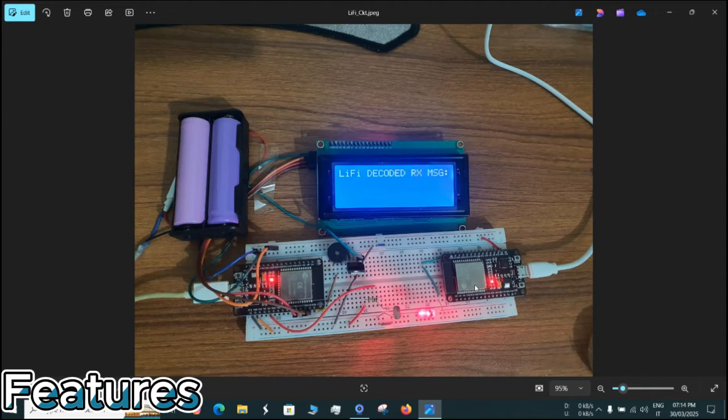So, as I've already told you, I will be transmitting a string or text from one end to another end. The building block of a string is a word. The building block of a word is characters, and each character has an 8-bit ASCII value. So transmitting a single character means transmitting a byte, or 8 bits, and we will be transmitting the bits using light pulses.